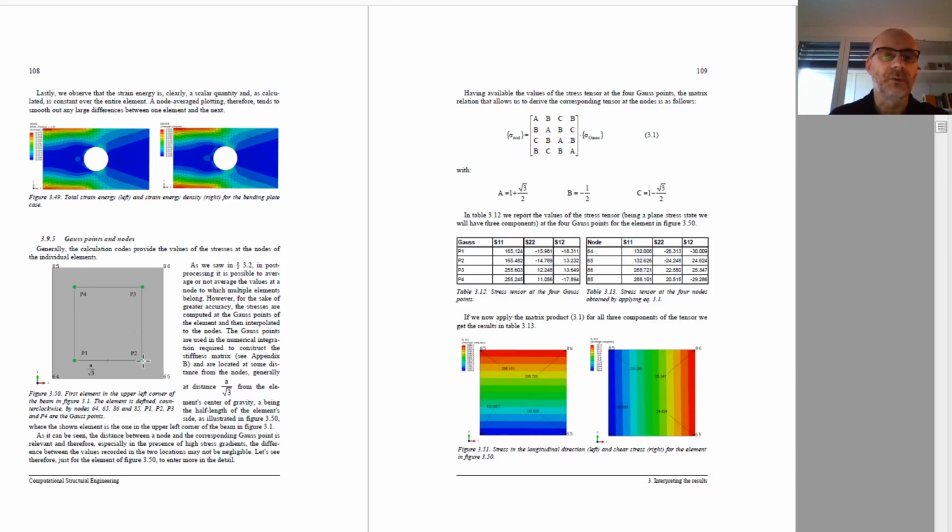And this is something new for the book itself, just the explanation on why stresses calculated in the Gauss points are different from stresses calculated in the nodes, and why this sometimes is useful to know, for example, when we have a perfectly plastic material, as we will see in chapter 13, the yield limit should not be overcome, of course, because that is the maximum, but then the stress is calculated in the Gauss points, and then it is interpolated through the shape functions to the nodes, and so it can be higher or lower.